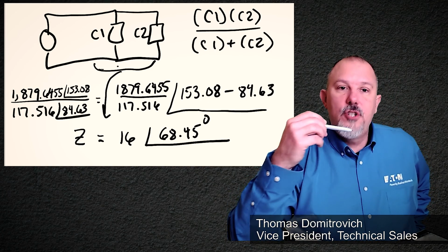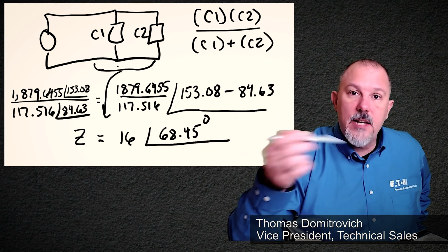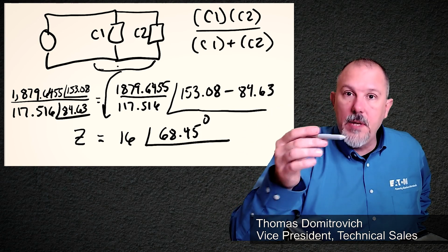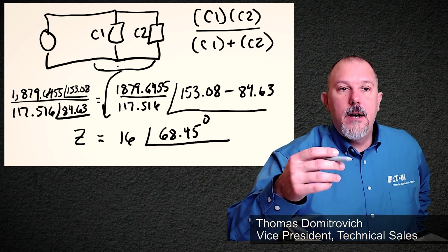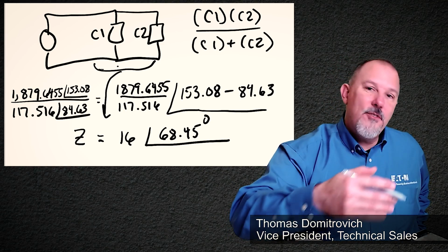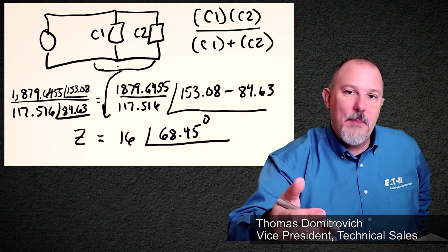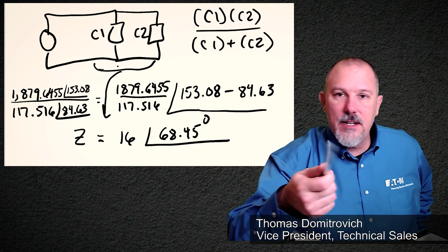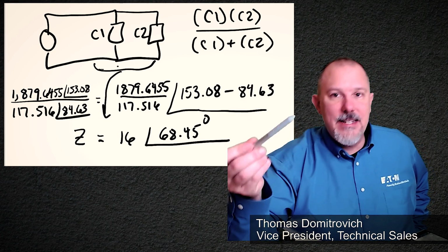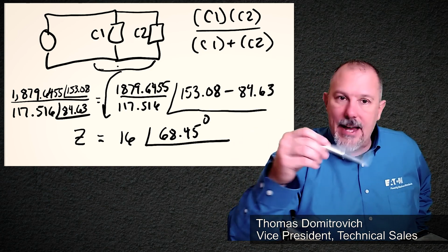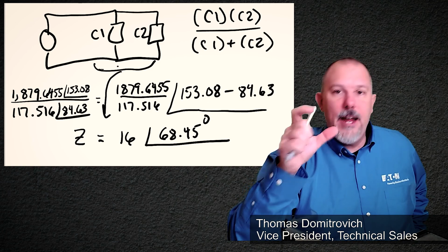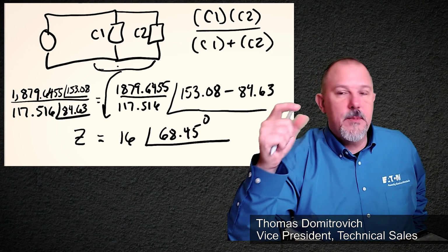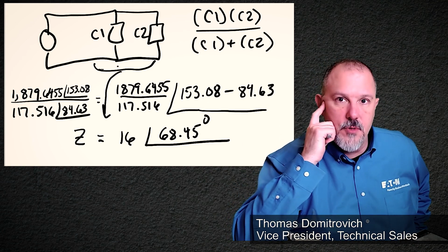If we are doing a voltage drop study, can we just use Z? Yeah, you'll have more voltage drop than what you actually have. And again, it'll depend upon all your different reactances and all your different impedances. I just had these two conductors. If I had a very high inductive and very low resistance, and I added more conductors in series or parallel, then the errors add up considerably, especially when you get into a large power distribution system.